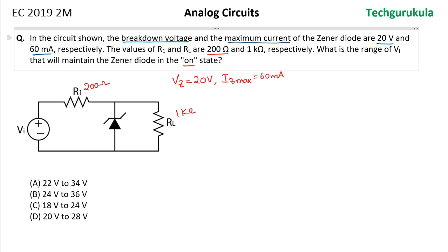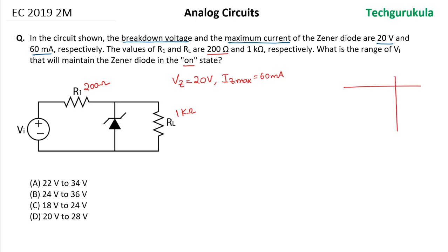So when we look at Zener diode characteristics, obviously in the reverse bias where our interest is, it enters into the breakdown region. When it enters the breakdown region, that's when we say the Zener diode is in the on condition. As the series resistance is not given for the Zener diode, we're going to take the Zener resistance RZ as 0, and we take this as Vz.